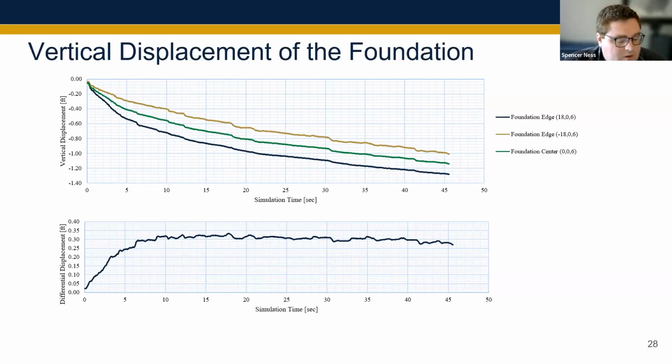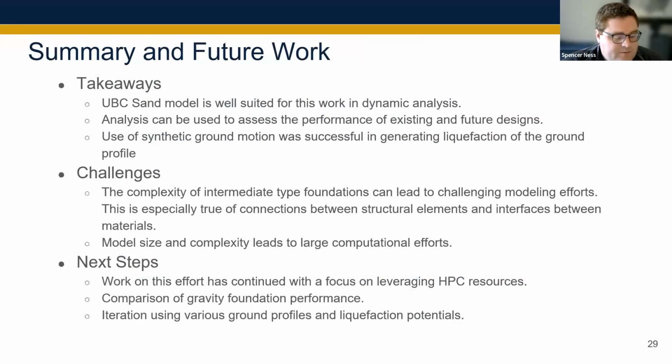So running a little bit behind here, but I just wanted to go through some of the quick takeaways that we had from this work. We found that the UBC sand model worked well in this dynamic analysis within Plaxis, capturing the behavior that we expected, and it made sense.